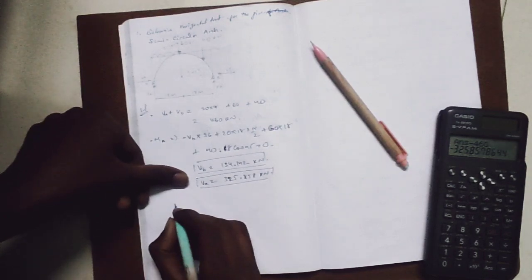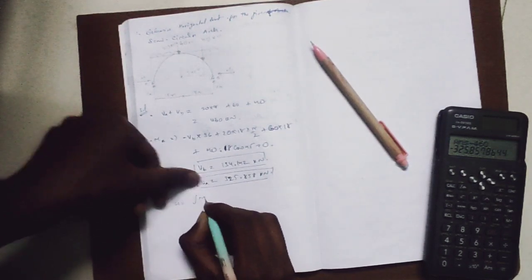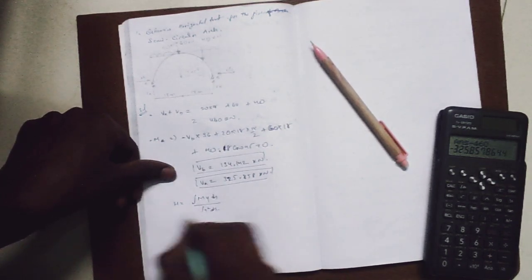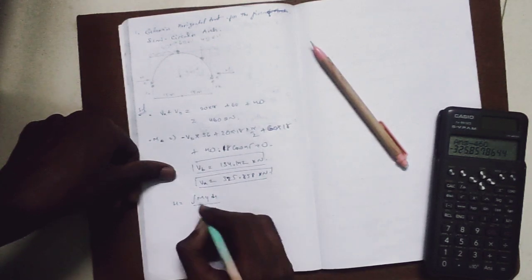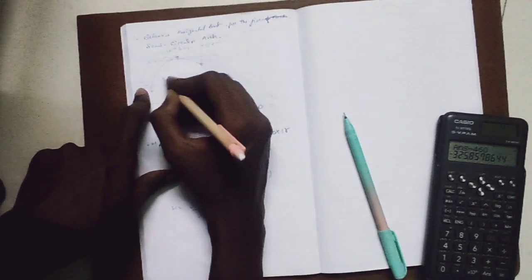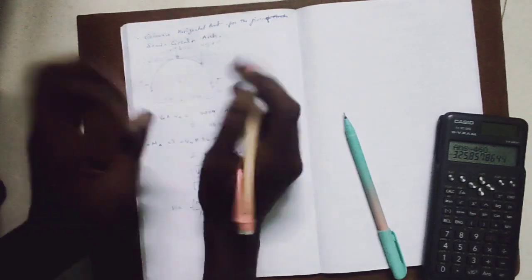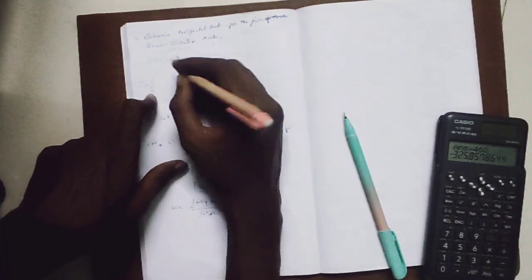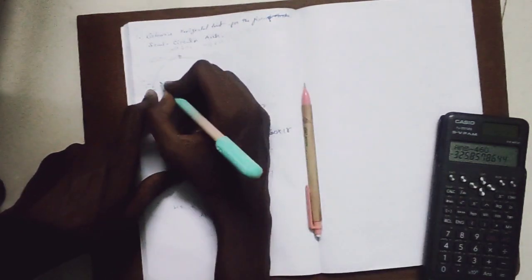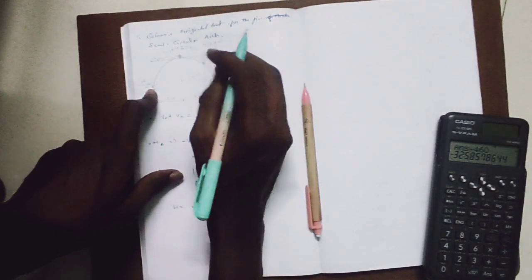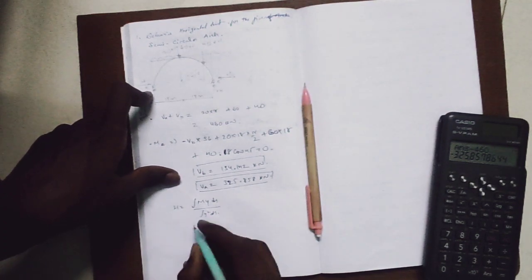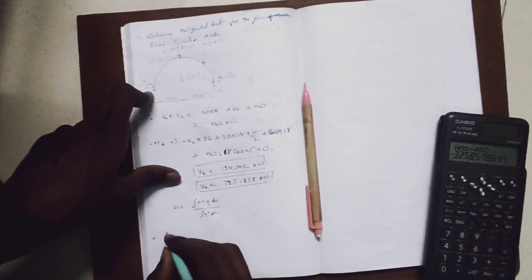Now we have H is equal to integral of M y ds by integral of y square ds. So we have to use this formula. First we have to find this M. Now we have to find M for this whole arch, right? It is not symmetric, so we can't write the limits directly. So we have to split our limits into some sections. So first we're going to write the numerator part.